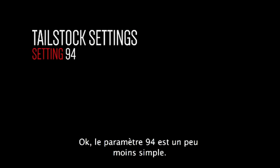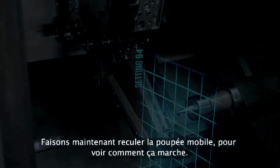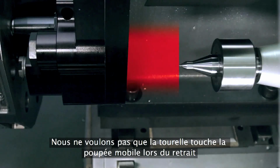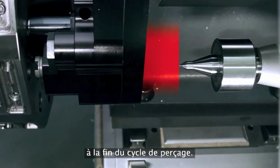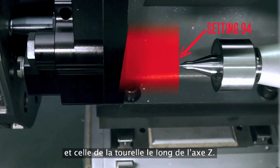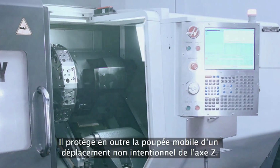Okay, setting 94 is a little trickier. Let's move the tailstock back so we can look at how it works. Say, for example, we need to drill the end of this part mid-cycle. We don't want the turret to hit the tailstock as we retract at the end of the drill cycle. Setting 94 represents the difference between the position of the tailstock and the turret along the z-axis, and it protects the tailstock from unintended z-axis moves.